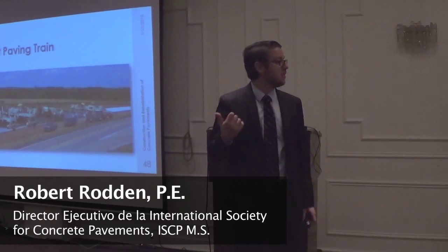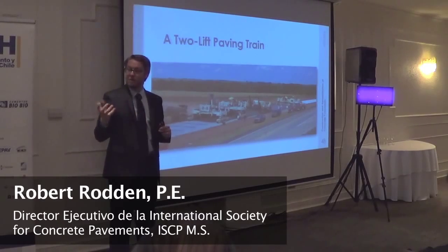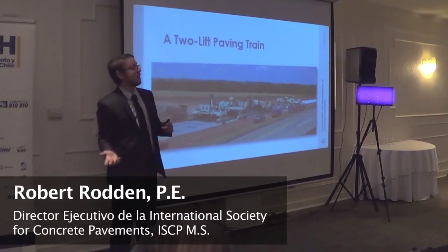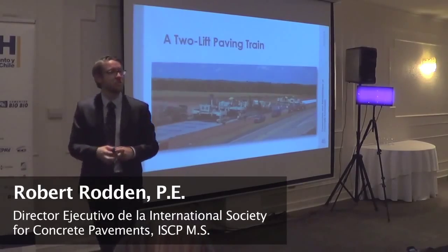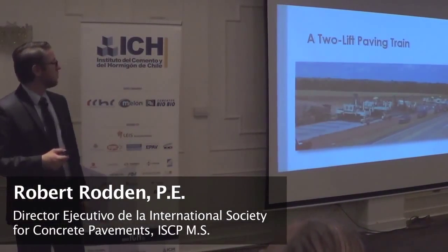So say we have a lot of limestone or aggregate that might polish easily. We can build the system to be three-quarters of that, and in the last quarter, we'll just pass by and use higher quality aggregate just to close off the surface, to cap the surface with a more durable material. So it could be economics driven, sustainability driven. We could just use fibers in one half the thickness and not the other half. We have opportunities to do a lot of different things when we functionally grade the system.